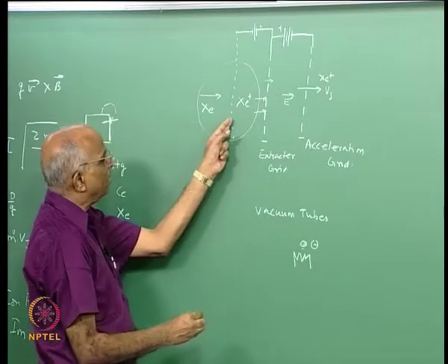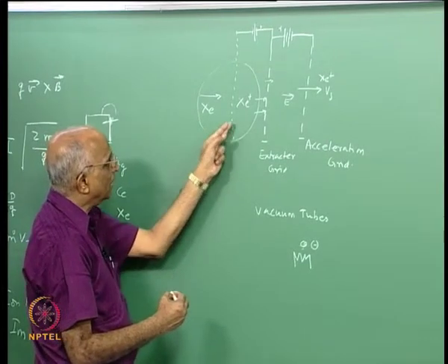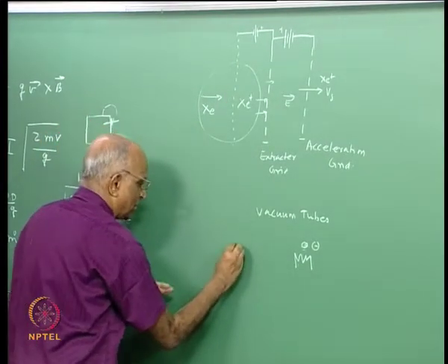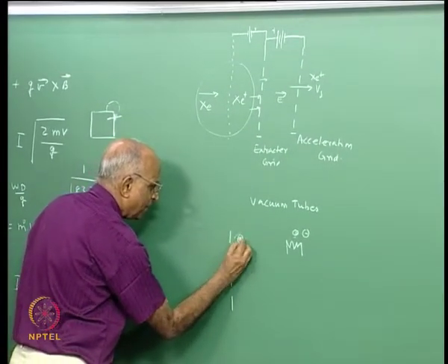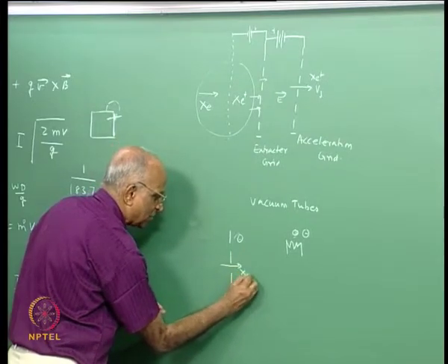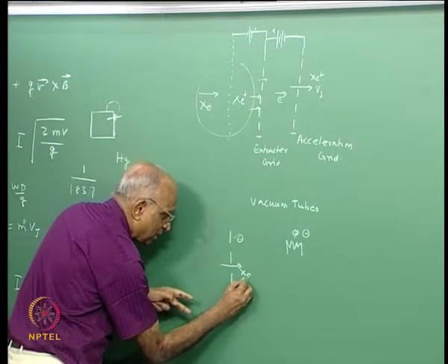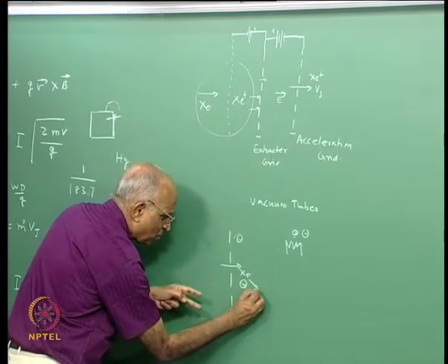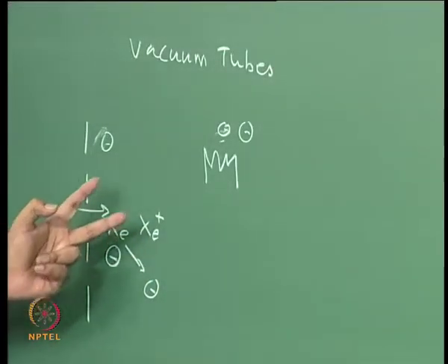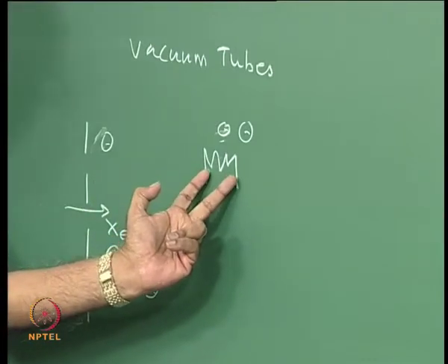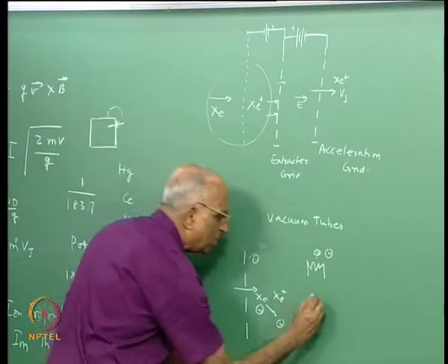Therefore, if I could have a grid made of tungsten or even molybdenum for that matter, and I heat this particular grid, maybe electrons are generated from this grid, and these negative charges, when they hit against the flow of xenon gas which I am passing over here, the neutral xenon atom is hit by a negative charge, and this knocks off one more electron over here, makes the xenon positive, and this is how I could create it using a sort of resistor which is heated, which I call thermionic emission.